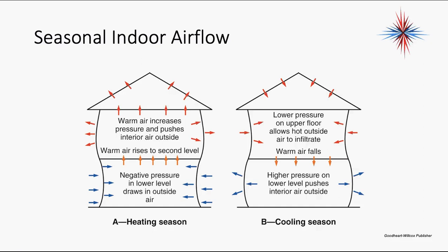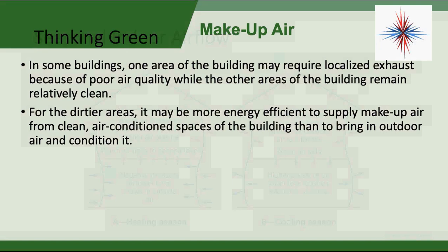When we're designing an HVAC system, we have to take into account these warm and cold airs coming in and out of the building, because that's building leakage. It is a heat load. It adds sizing and BTU requirements to our air conditioning and heating systems. We have to have makeup air.